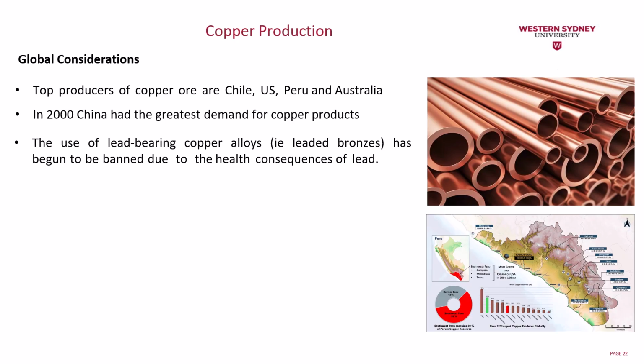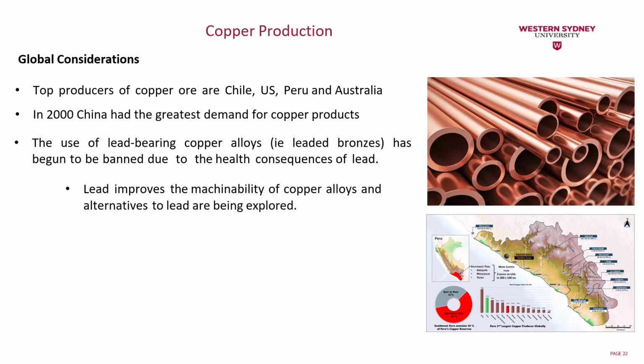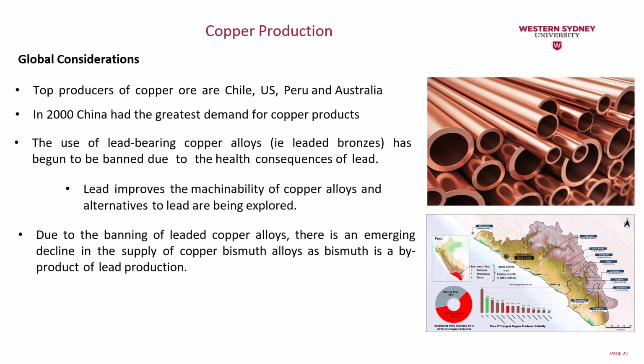The use of lead-bearing copper alloys, like leaded bronze, has begun to be banned due to the health consequences of lead. Lead improved the machinability of the copper alloys, and alternatives to lead are being explored. Due to the banning of leaded copper alloys, there is an emerging decline in the supply of copper bismuth alloys, as bismuth is a byproduct of lead production.